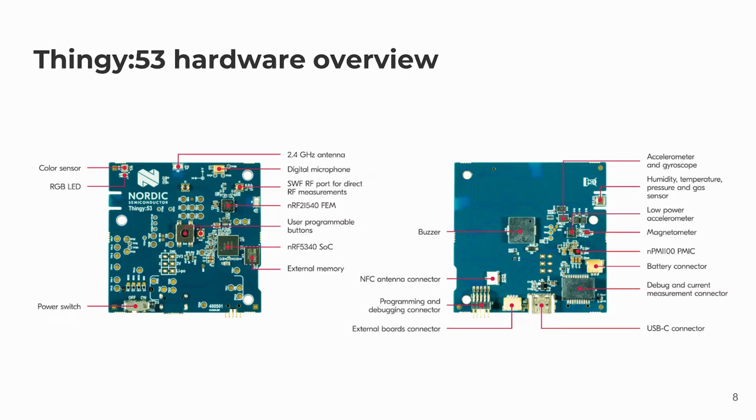It also has a highly efficient network coprocessor. That's also an Arm Cortex-M33 processor, and we recommend that you put our tried and trusted protocol stack in this processor and leave the networking up to us, but it's fully open and programmable, so you can do whatever you want with this coprocessor. Then it comes to the multi-protocol radio. It supports Bluetooth LE, Bluetooth Mesh, Zigbee, Thread, and by extension Matter, and also less common standards like NFC and ANT.